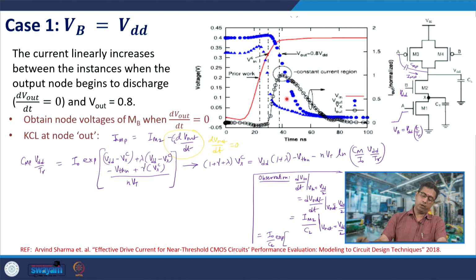Now, this is valid across fan out loads, because of the input-output one to one correspondence. There is also another reason: that one to one correspondence is accurately valid only for inverters. For NAND gates it is valid, but only approximately. But there is another factor which plays out here. At this point the input is now stable, at a certain value, and the output voltage is falling.